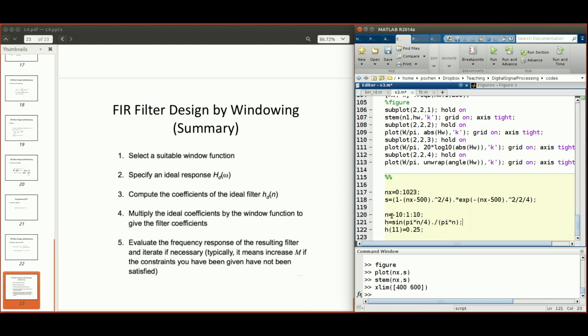And because this is actually a finite interval, right? It goes from just -10 to +10. So this impulse response computed using this finite interval is going to be finite duration, right? It's not a sinc function that's oscillating forever. It only goes from -10 to +10. And this line is just to get rid of the not a number at the center of that sinc function, right?